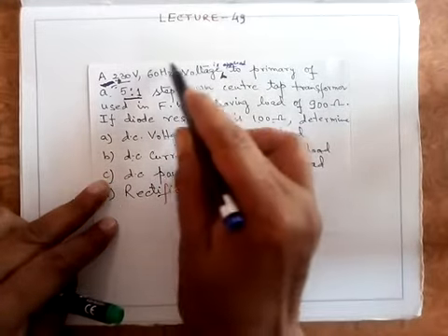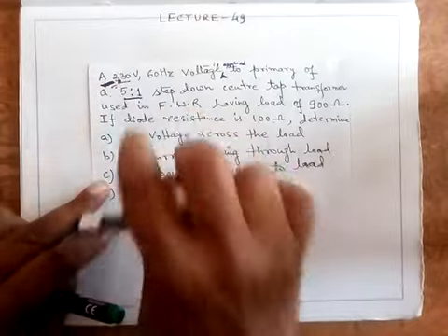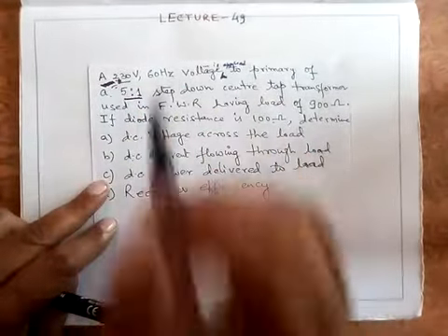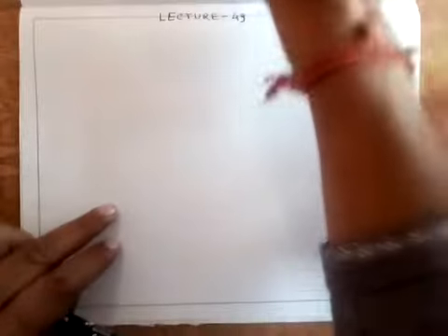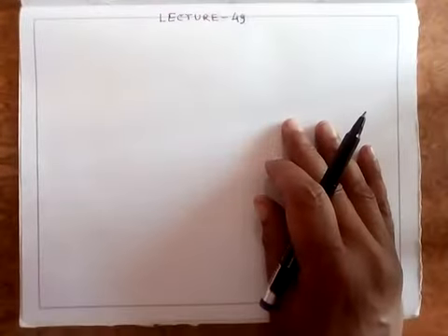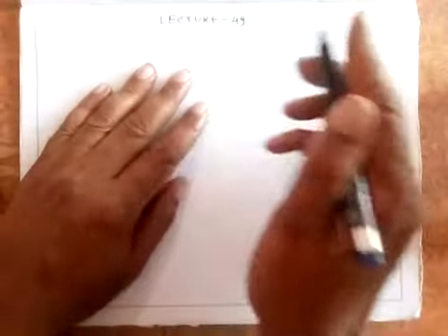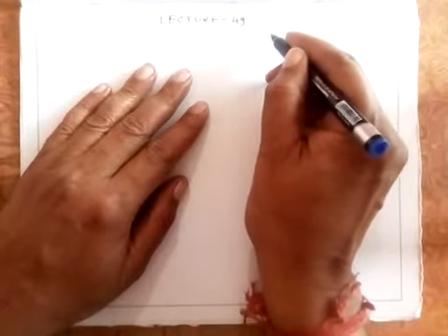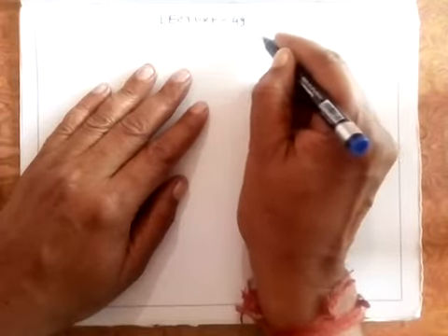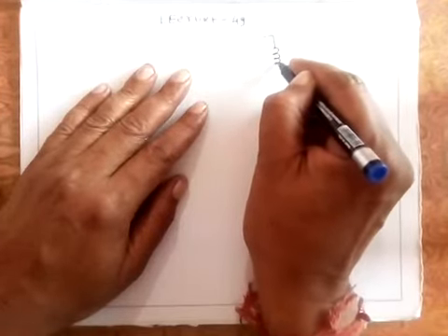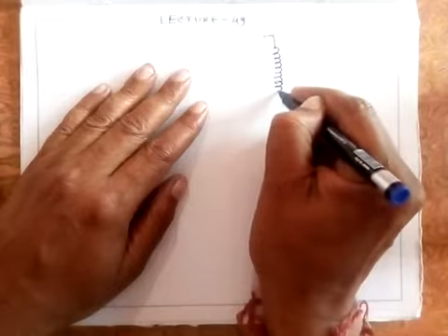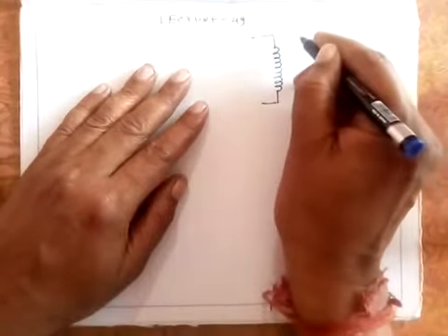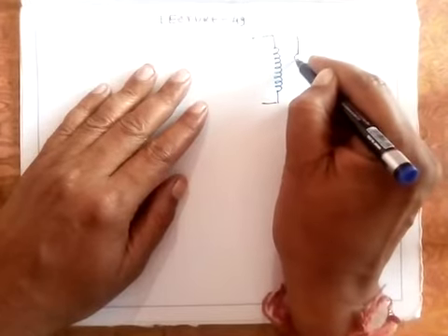Very first thing, a transformer is used and some voltage is applied to the primary of it. So let me draw the circuit of it first of all. For a center tap full wave rectifier, we have done this many times. So the circuit is like this. You have a center tap transformer with a primary winding, and then you have a secondary winding which is center tapped.